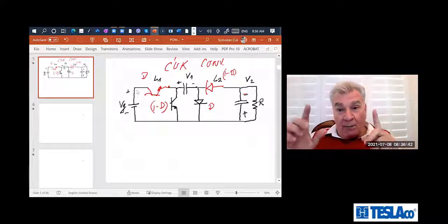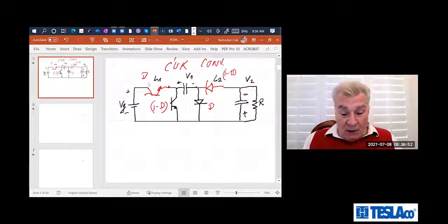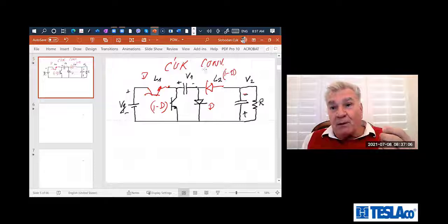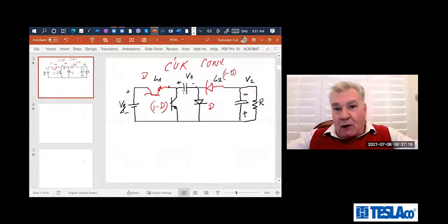Remember I told you capacitive switching only, what is called capacitive switching, what was introduced, is inefficient, because when you turn on a switch, this will force the diode, and you will charge this. But you will charge this and then you will discharge in this way, so this will be like capacitive. This is what the people did with many switches and capacitors. I'm doing it here with a single capacitor. You see, switched-capacitor converters had 6 or 8 switches and 6 or 8 capacitors, right?